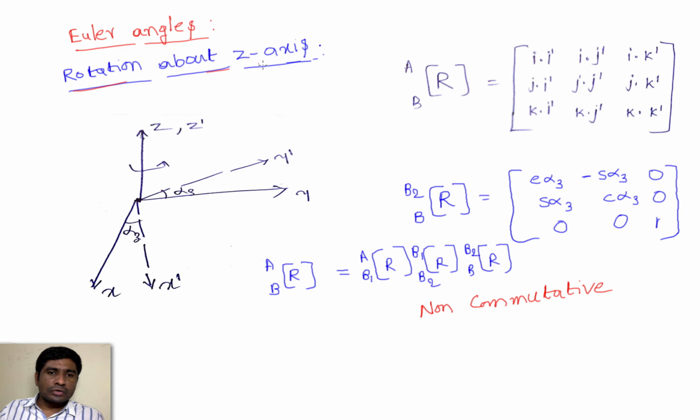Now I will rotate about the z-axis. So this is the z-axis, and I am rotating like this. Again, this is the right hand thumb rule. So from x to y, so that z is going up here. And in this case, this x dash as well as y dash are in the same plane of xy, so that x dash, y dash, all these four lines are perpendicular to the z and z dash. That means whenever we need to find the angle between these combinations, then this is 90 degrees.